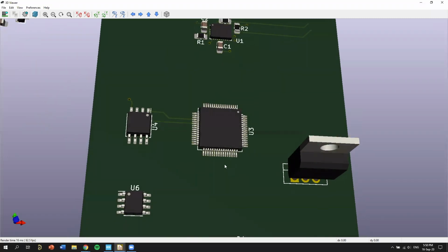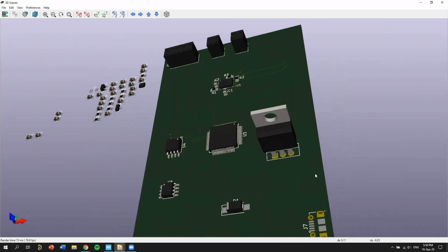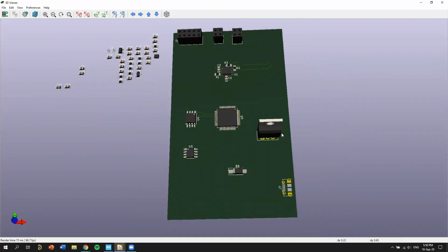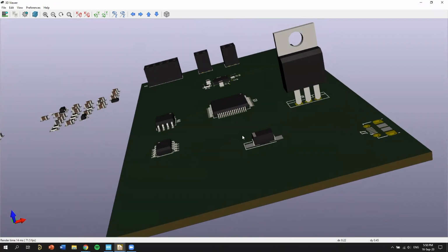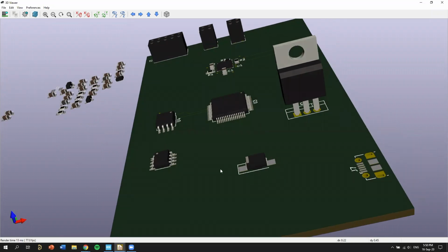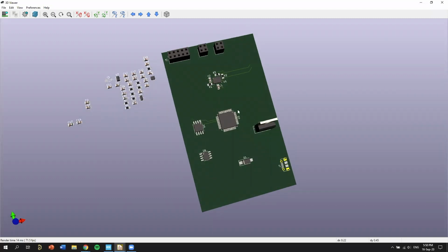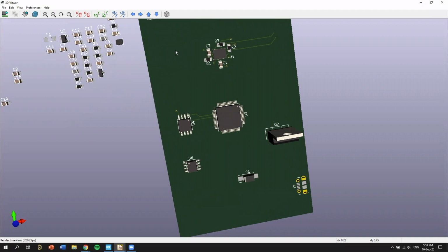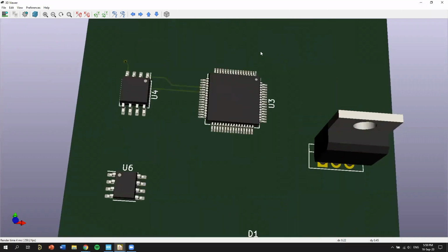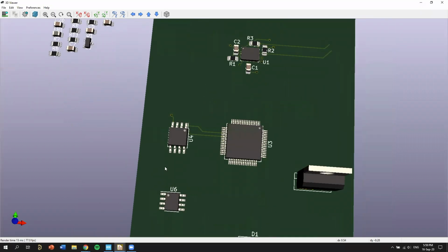you can see how you can start to build up a full design. I'll start with the big components. Just place them around and see, it's a weird diode, like really big pads. See where they're fitting, see where everything connects in a higher sense. Put components that are similar, or meant to be together, together. For example, for our IMU here, we put all of the resistors and capacitors around it that we know we're going to need. And do that for every single chip first.